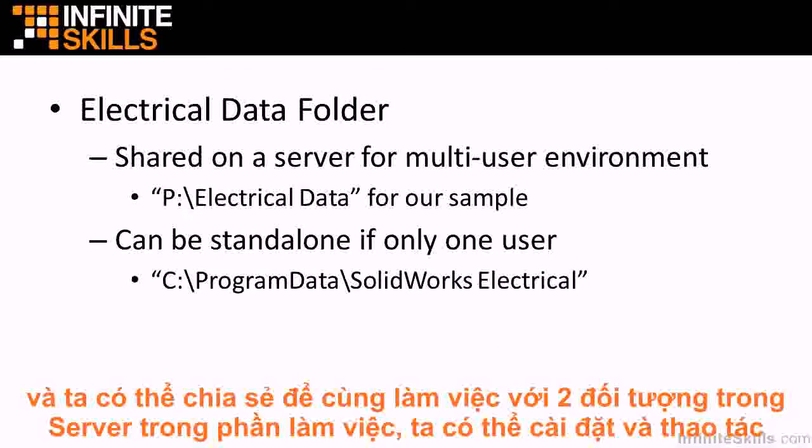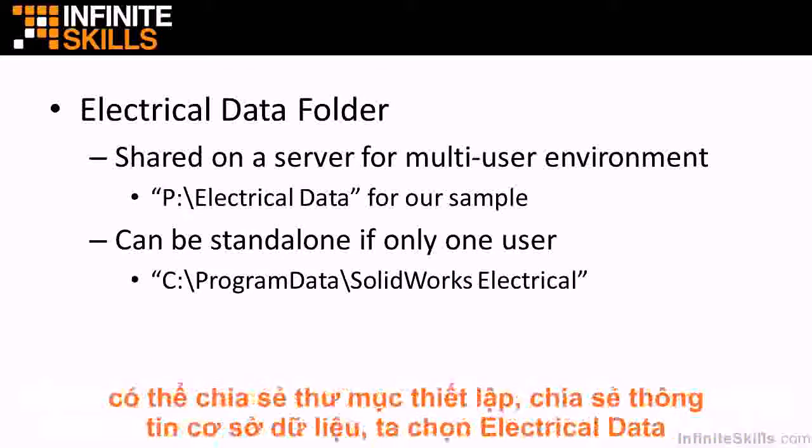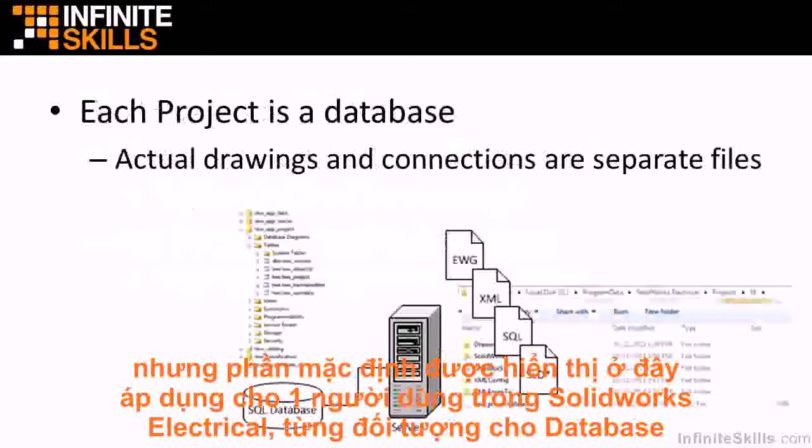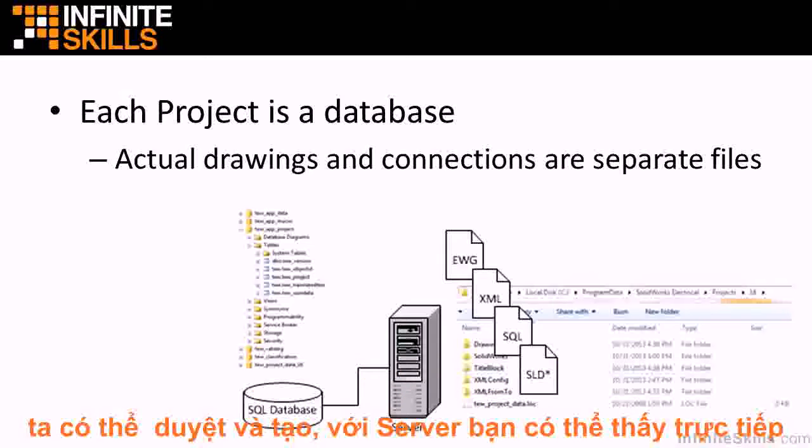On the server, or on your workstation if you install it standalone, is a shared folder set up with all of the blocks, symbols, and shared information that does not live in the database. In our installation, we've chosen to put it in P electrical data, but the default data directory is shown here if you're running only as one user. In SOLIDWORKS Electrical, each project is a database. So if you were to browse in to the Microsoft SQL Server environment, you would actually see a database file for every new project that you create. And then on the server, you would also see data directories.